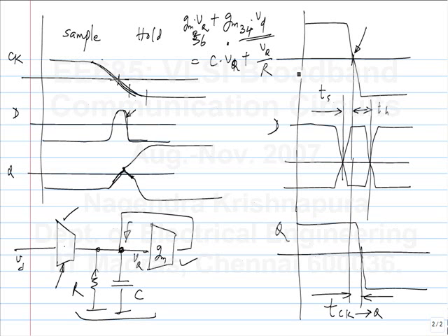Is this clear? And how does the size of 5, 6 influence the hold time? Gm5, Gm6, do they have any influence or not? Yeah, hold time would be smaller. During this period, this part is trying to regenerate the voltage, whereas this is trying to take it in the opposite direction, perhaps in the direction of the data.